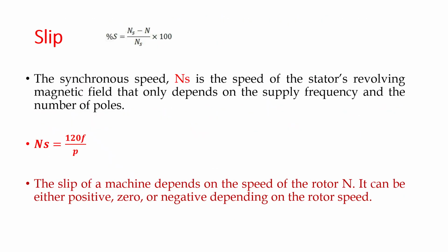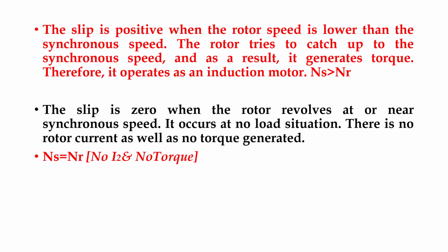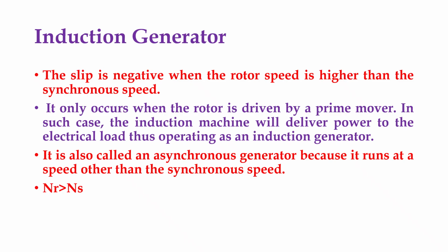Then when we are talking about the induction motor, the slip will be positive, where the synchronous speed is greater than the rotor speed. So the slip will be positive, and this will act like an induction motor. And coming to the asynchronous generator, the slip will be negative.